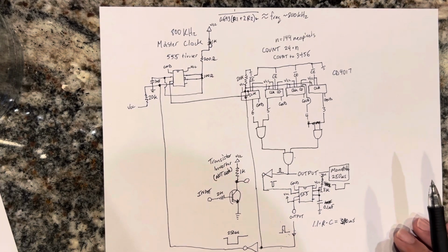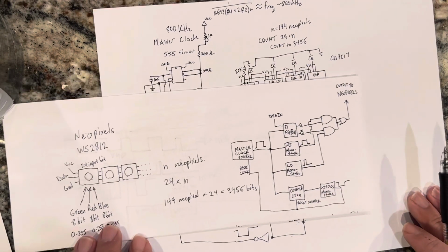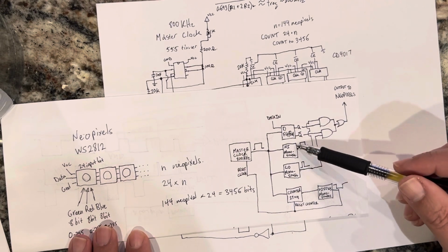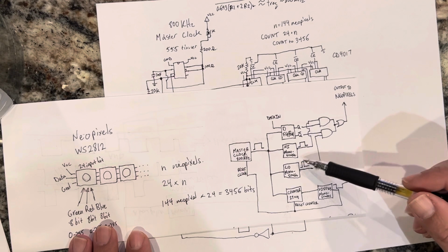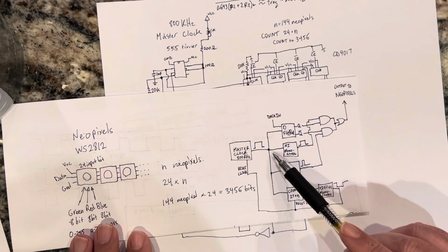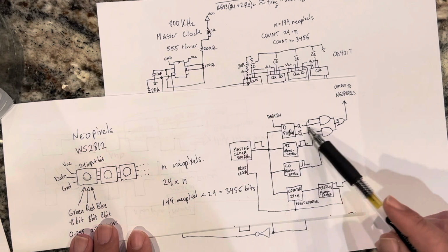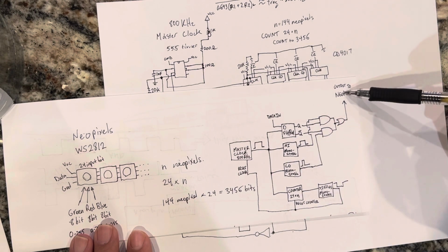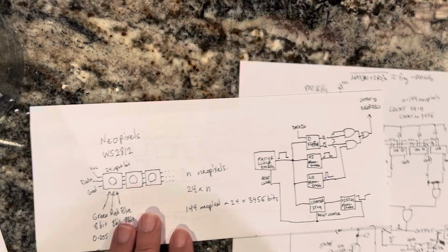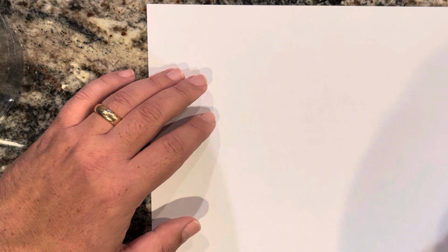So in this video, we're going to talk about the next part of the circuit, which is the D flip-flop. And if I get to the monostable pulse generators, then that's what I'll do. The purpose of the D flip-flop here, as we discussed in the first video, is basically to synchronize all the pulses together in order to create a nice synchronized output to the neopixels, and it allows for the data in. So now we are going to talk about the D flip-flop.